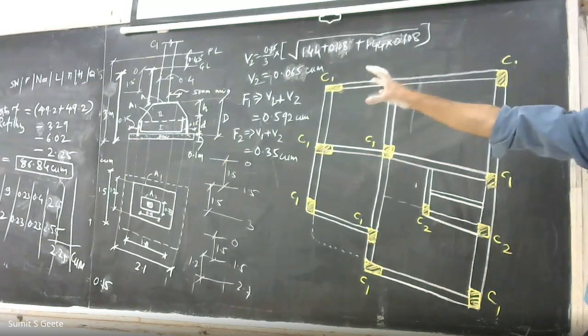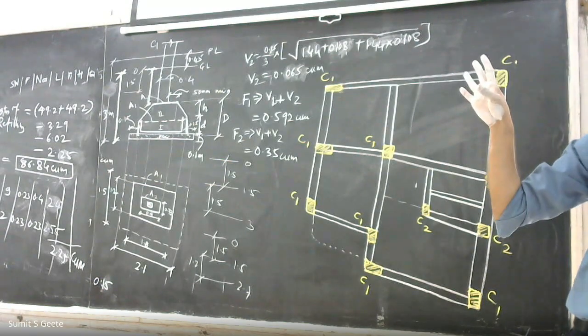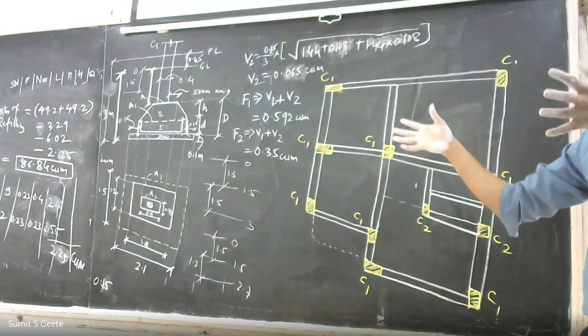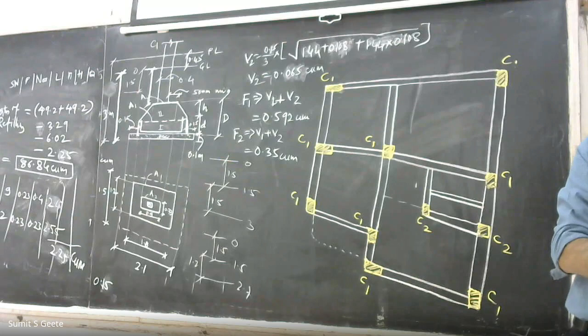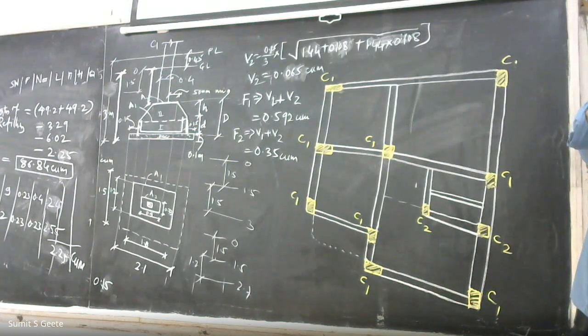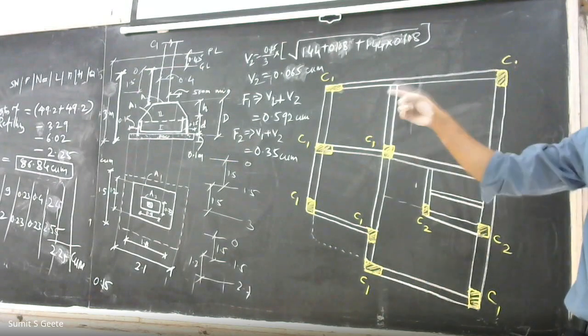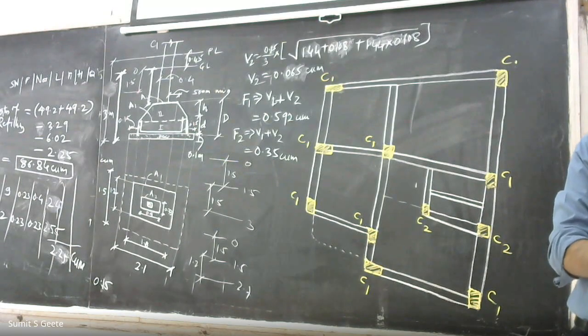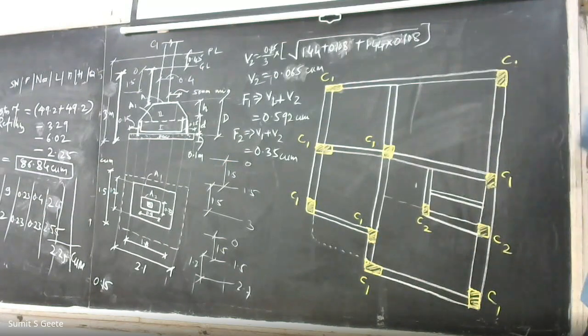तो कुछ लोग इसको ऐसे कैलकुलेट ना करते हुए जो भी आपका एक्सकेवेटेड मटेरियल आता है, रिफिलिंग का मटेरियल, उसको सिंपली कंसीडर करते हैं 60%. मतलब अगर आपने टोटल 100 क्यूबिक मीटर का एक्सकेवेशन किया, रिफिलिंग को कंसीडर करते 60% ऑफ एक्सकेवेटेड मटेरियल. अब ये 40% मटेरियल कहां जाएगा? That material is transported from your site to some other place for the stacking purpose. तो यहां पे लिखो भी: what quantity of material transported from site to some other place for stacking.